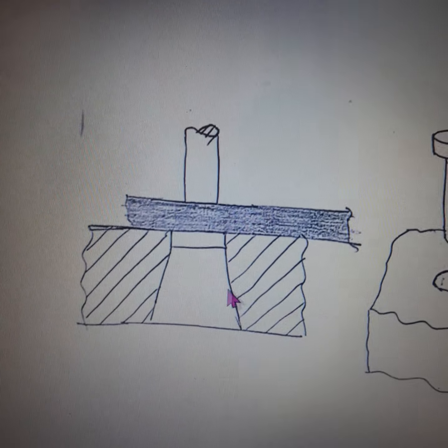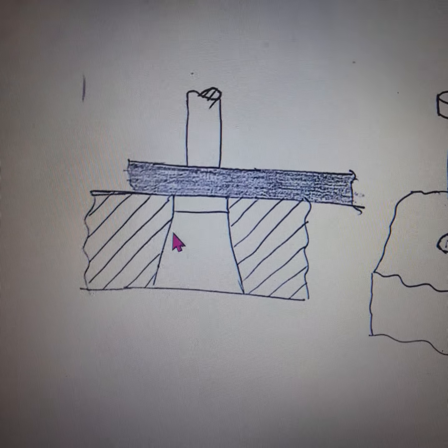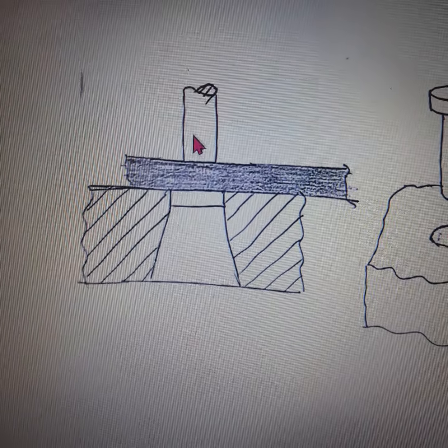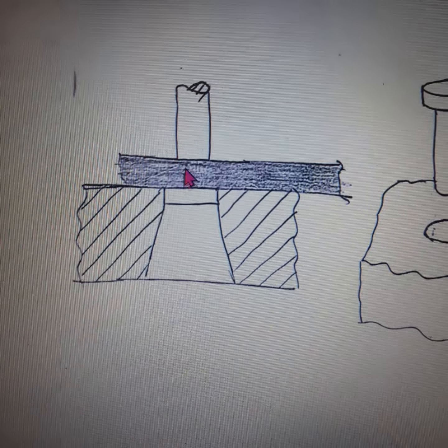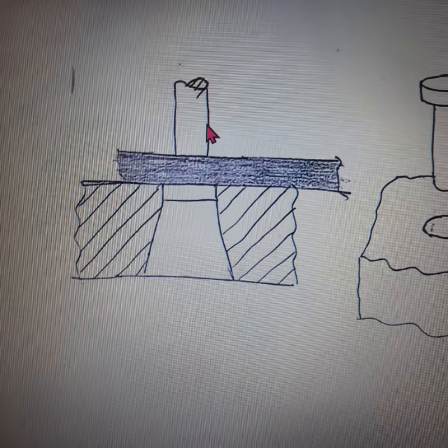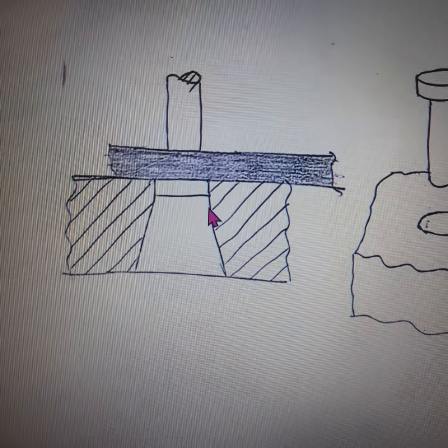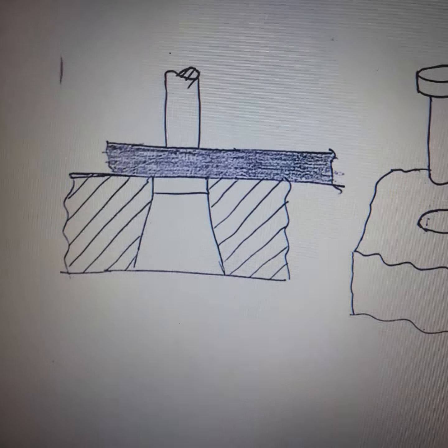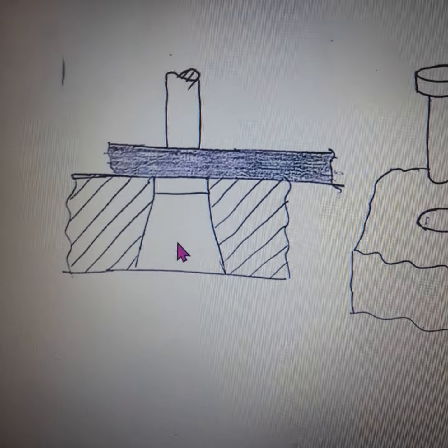If you look at the sectional view, the punch and die have got a small difference in size. So in the case of a piercing, the punch is made to the size of the drawing and the die is made bigger by an amount called die clearance. So the die clearance is the difference in size between punch and die of a stage.